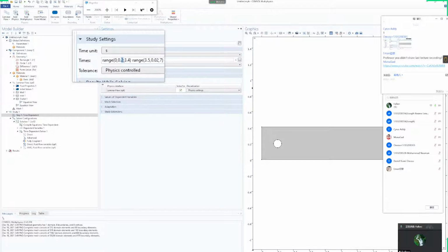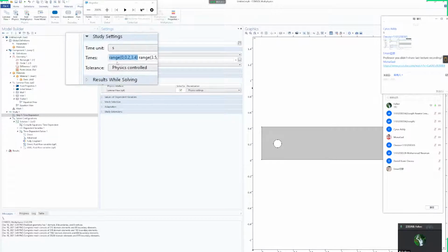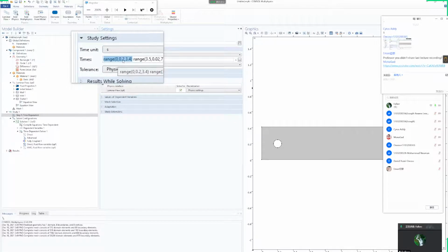That means in the early part of your calculations, the flow is not steady. So you should let the software some time to make the flow steady.